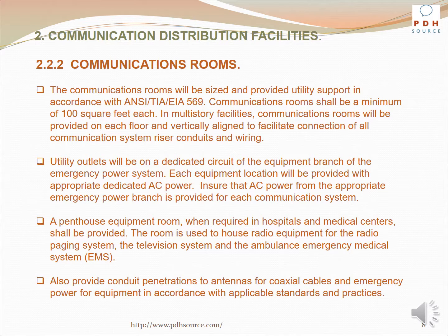Utility outlets will be on a dedicated circuit of the equipment branch of the emergency power system. Each equipment location will be provided with appropriate dedicated AC power. Ensure that AC power from the appropriate emergency power branch is provided for each communication system.